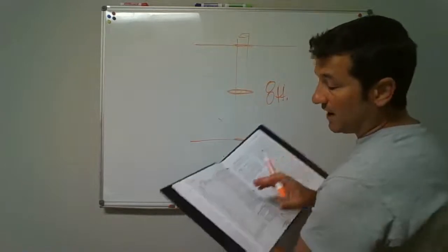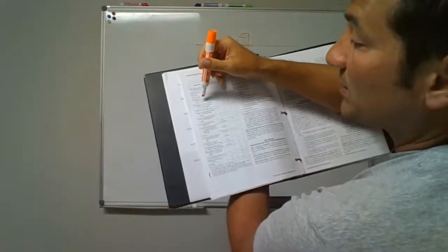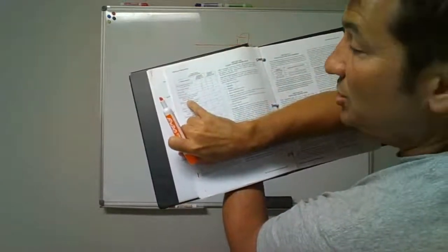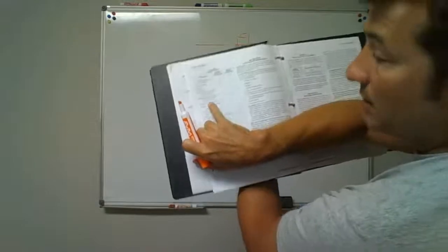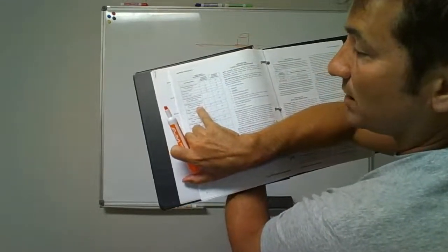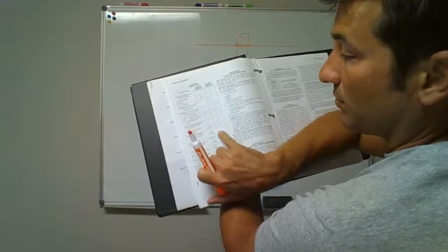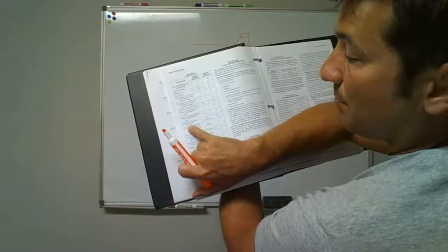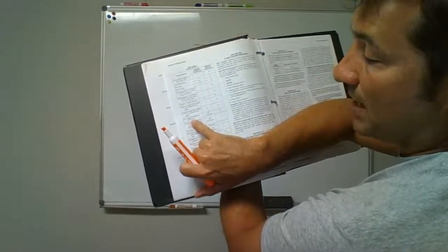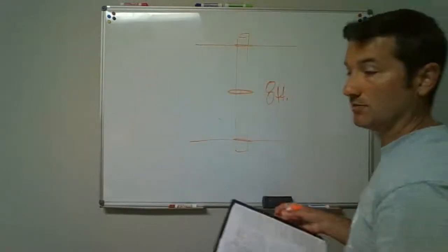So you can just find it. Find the material you're dealing with. Some of them, if it's CPVC, there's one that says if it's 1 inch and smaller. There's one here that will say if it's 1 1/4 inches and larger. You've got to go with those, okay? First one is horizontal pipe. Second one is if the pipe is going vertical. We're going to use a lot of PEX piping. So the horizontal support spacing for PEX is 32 inches. Okay, that's how you're reading that chart.